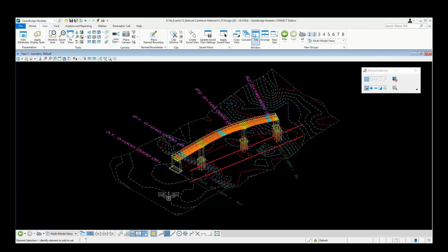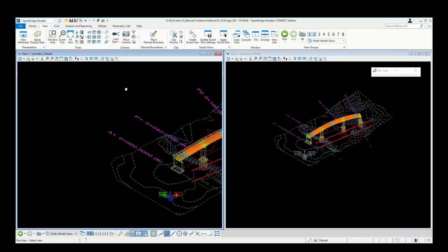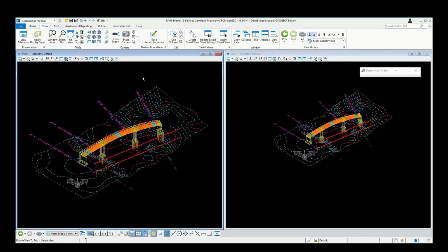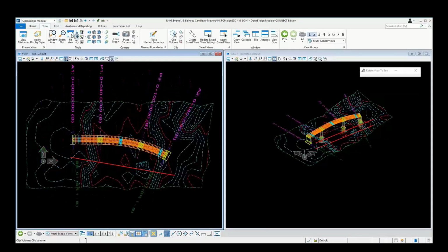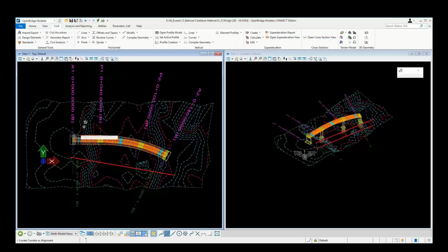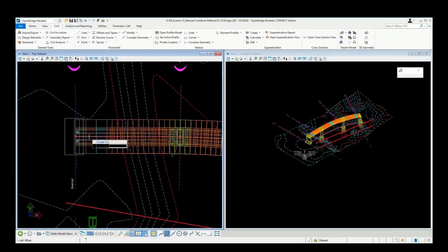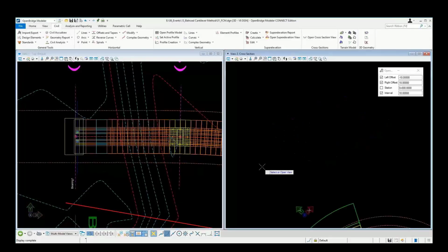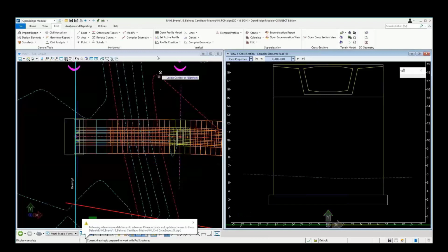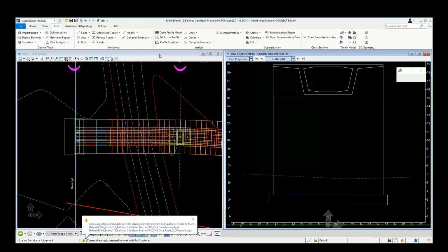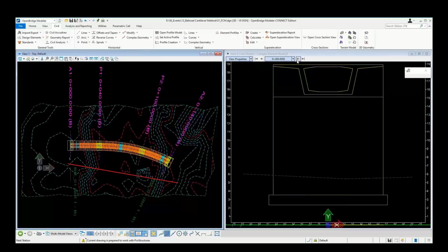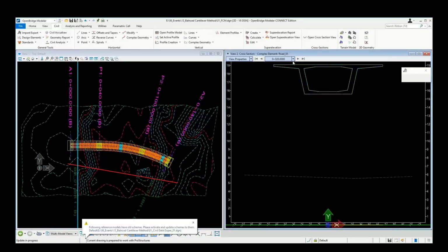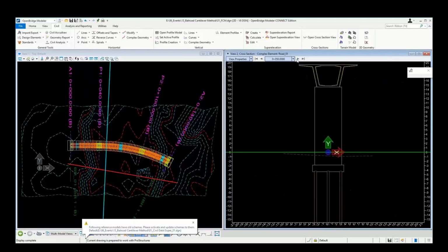I'm going to explain how to define super elevation using the reference drawing that was generated from OpenBridge Designer, and specify left and right boundary, and select a starting station and step spacing to produce the 2D cut drawing, and verify the 2D cut drawing. You can confirm the superstructure didn't define any segment.